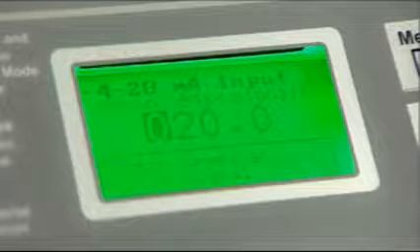Input a milliamp value of 20 to define a high point on the slope. Input the value of 20 for the output percentage of speed required at the high milliamp value. Note that to achieve a 5-to-1 ratio, this value must be 1/5 of the motor speed in the primary pump. Exit the menu system.